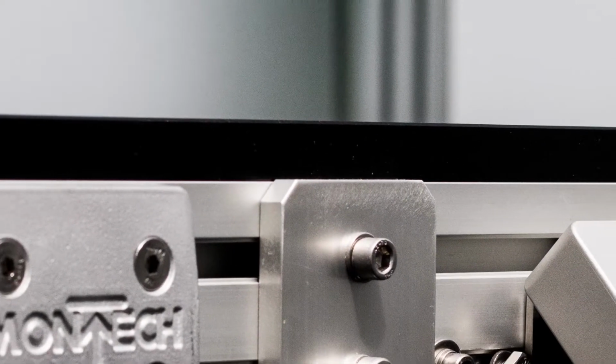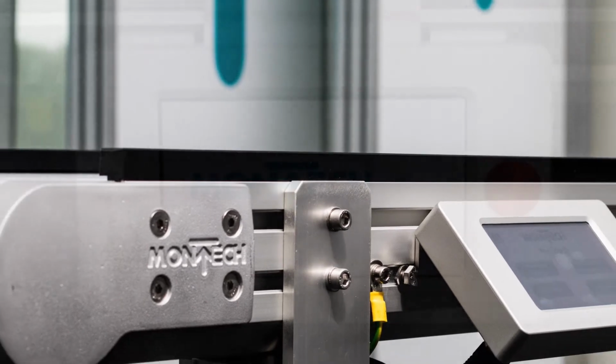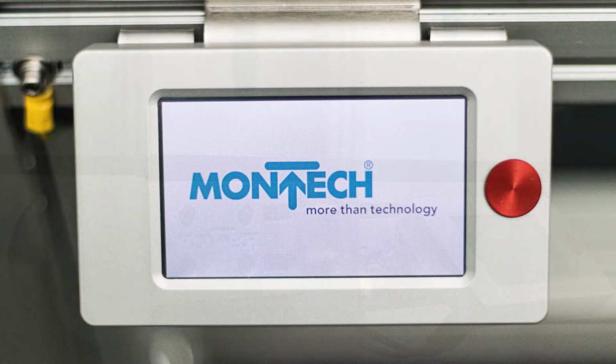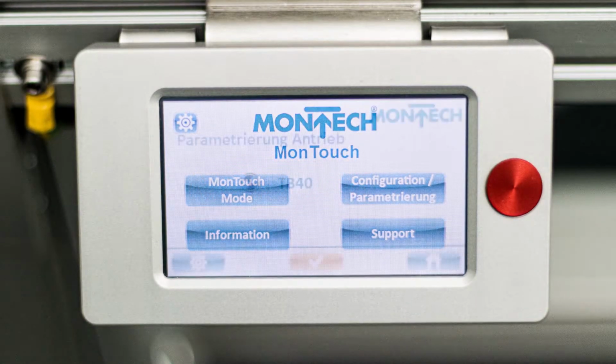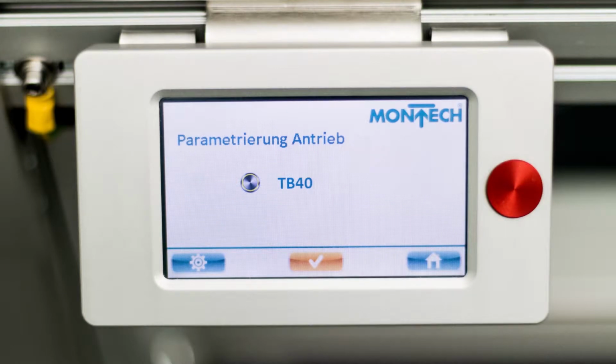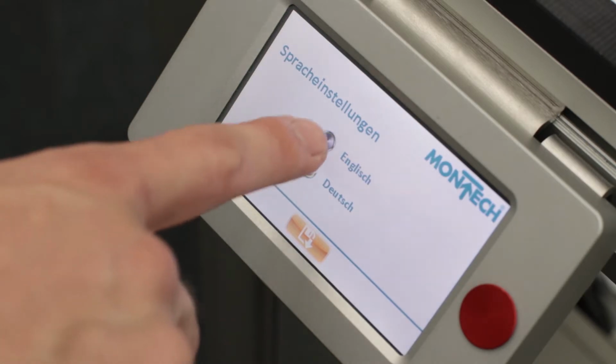When you connect the MonTouch controller to your TB40 conveyor, the initialization screen will appear on the display. Depending on the saved operation mode of the drive, the user interface displays MonTouch operation or parameterization. If this is not displayed, please check the connections of the cables and the power supply unit. You can choose between English and German operating language.